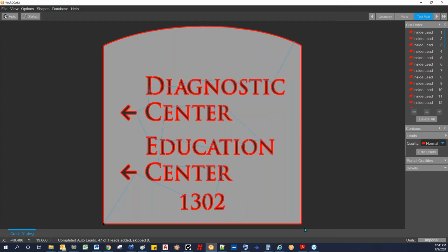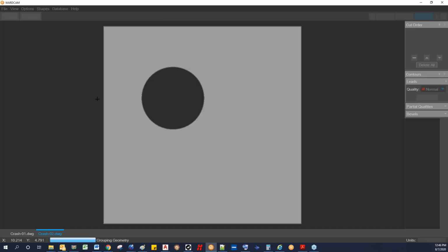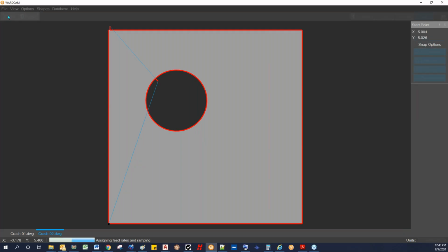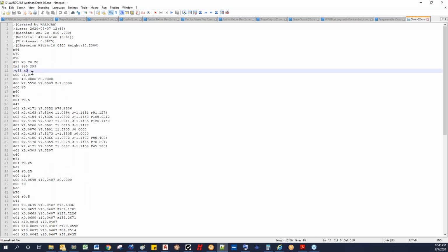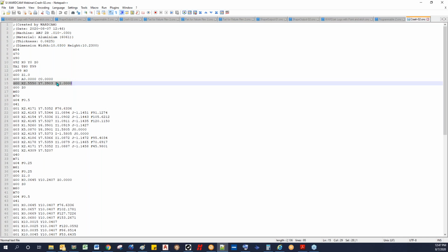So for example, a part like this, we look at it and it looks fine. Hit our next button, and we go through and everything's good. Hit our next button, hit our CNC file, and save. Now we've got our initial up there that we put in, and then it rapids, and you see on this rapid move it actually wants to go down to Z of -1, which would, of course, drive your nozzle through the material, which would be bad.